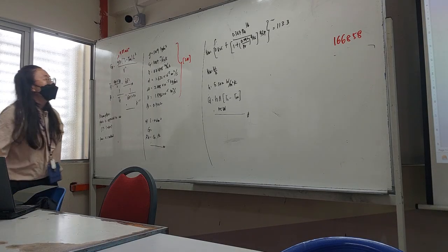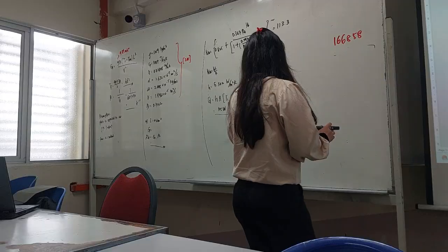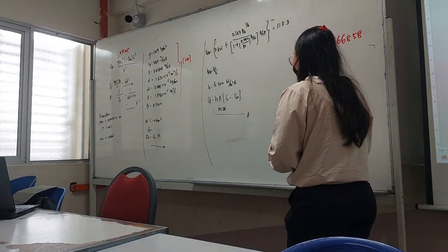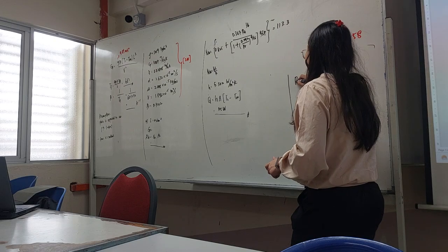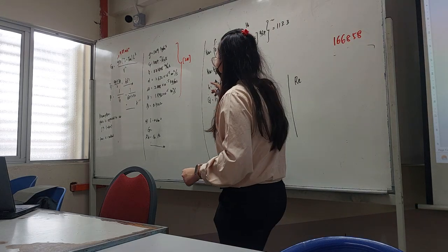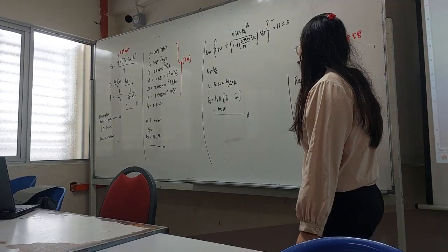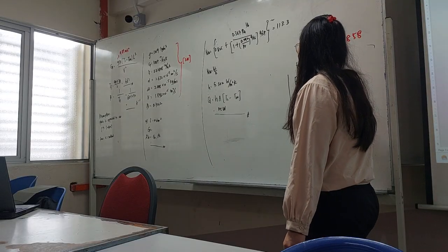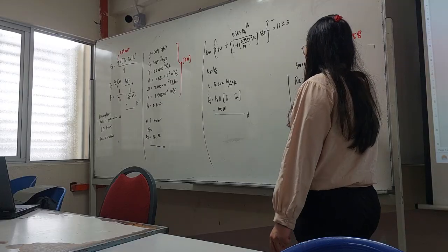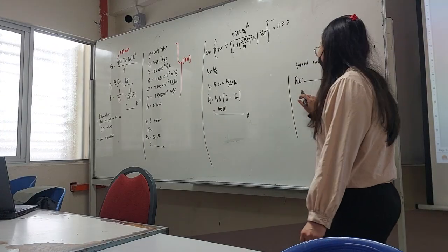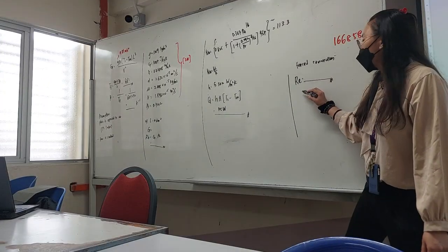And there is another possibility also. Let's say this is forced convection. Basically, you need to calculate the Reynolds number. For natural convection, you calculate the Rayleigh number. But if this is forced convection, you calculate the Reynolds number. Then you identify whether this is turbulent or laminar.